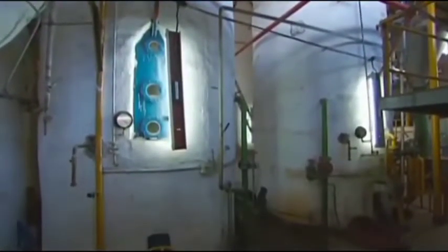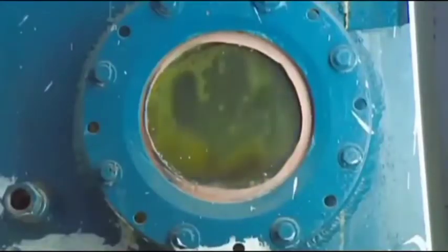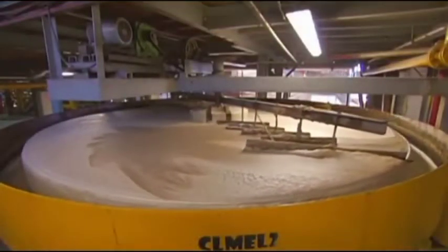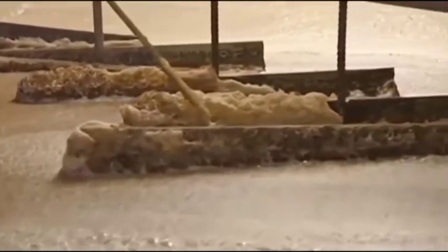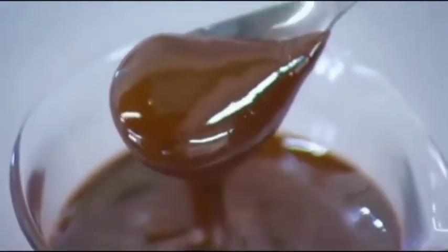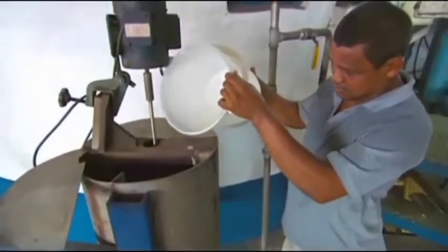Shell. To obtain good results, the roller of the mill unit must be able to grip effectively and not slip. This can be done if the roll material or roll shell is sufficiently coarse. The materials commonly used as shells are coarse-grained cast iron and fine-grained cast iron. Coarse-grained cast iron will produce a shell with a fairly good rough surface, but is less strong and breaks easily. Fine-grained cast iron has better strength, but the resulting surface is smooth, so it needs to be roughened in operation.